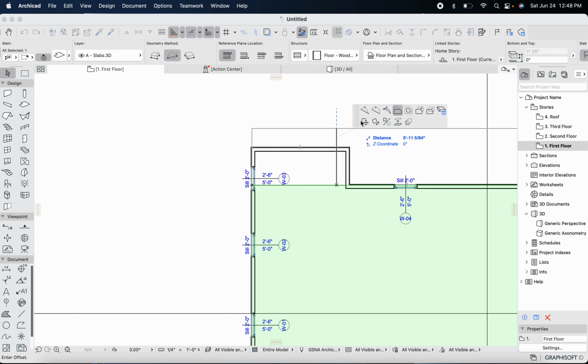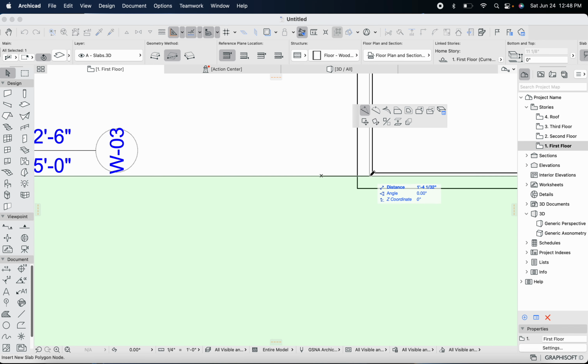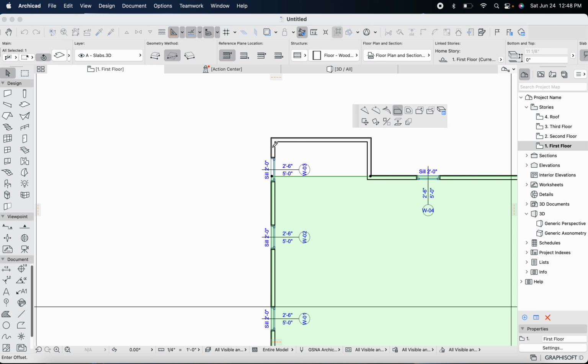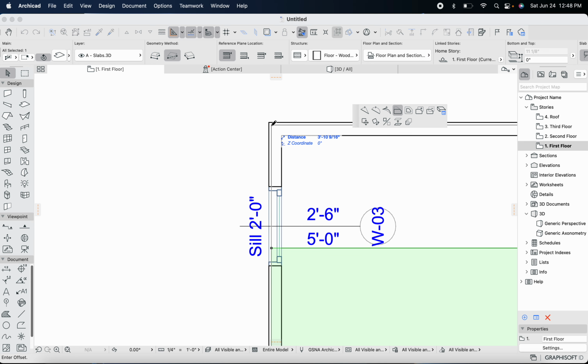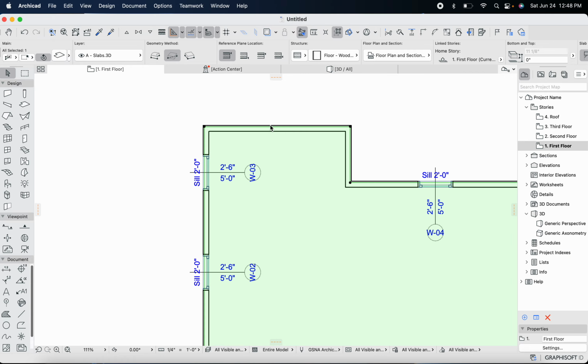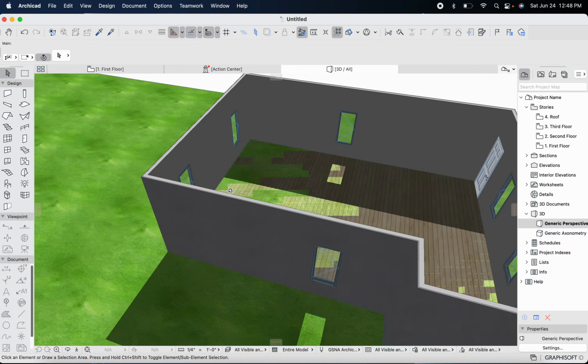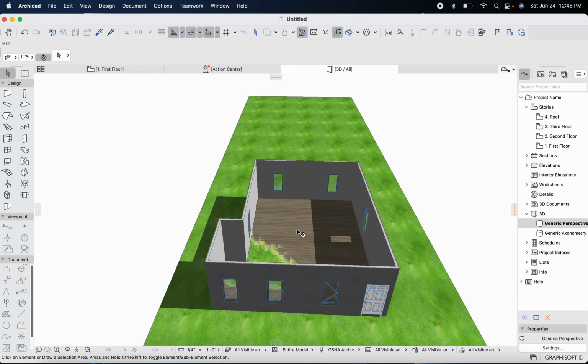And then if you click this edge and then click this feature here, it says insert new node. I'm just going to insert a new node there, and then I'm going to offset the edge again by selecting the edge and then clicking the offset edge function and just dragging that out like so. So now we have the floor covering our entire indoor space.